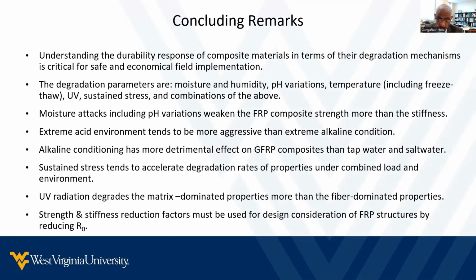Moisture attacks, including pH variation, weaken the FRP composite strength more so than the stiffness aspect of the composite, because the stiffness is a function primarily of fibers than the resin.